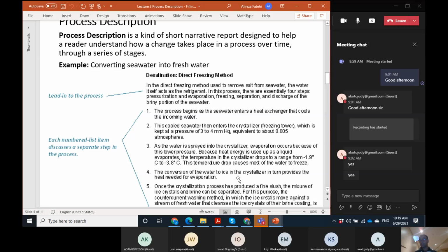This is the responsibility. Sometimes the explanation is not clear. You are not going to generate or assume some consideration for that. We should ask the operators. We should return to the mechanical engineers. We should return to the process engineers and ask them, okay, what should happen? For example, here, it just said that we need the control to be in this range. But what is the accuracy that they need, and how much fluctuation is acceptable, or something like this?